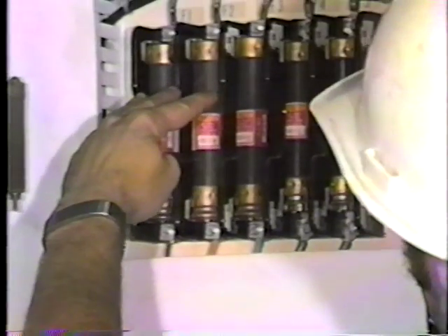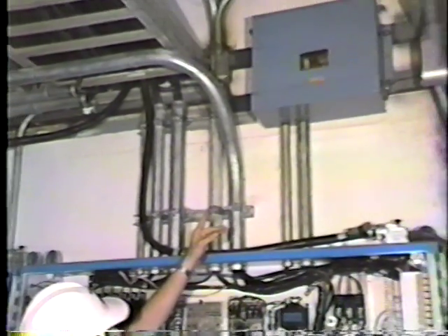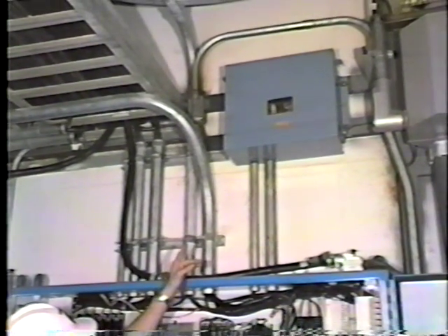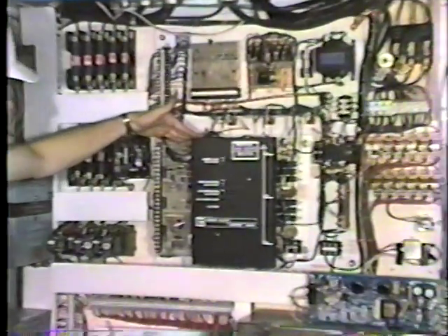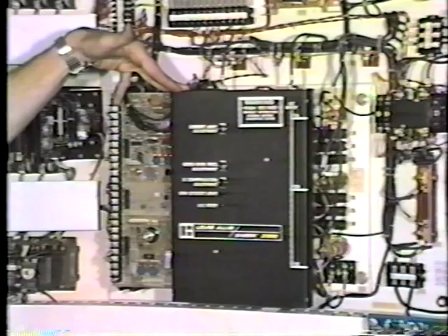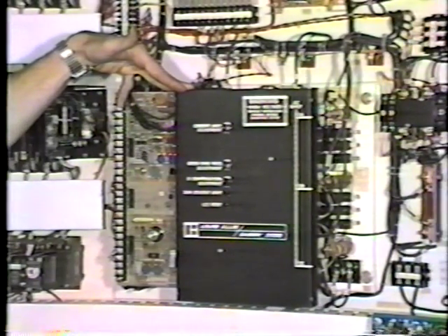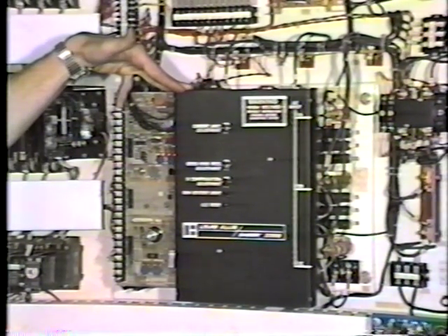The first three feed power into our classifier drive transformer, a 15 kVA transformer, and in turn are fed back down into our spinner drive. Where's the spinner drive? The spinner drive is located right here. That is the Sabre 3300 DC drive, 3-phase drive.